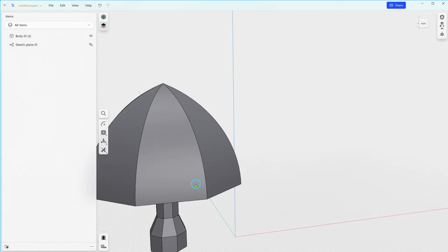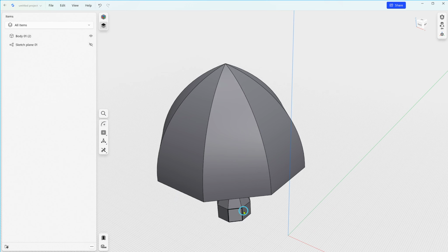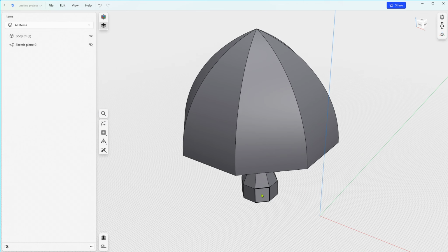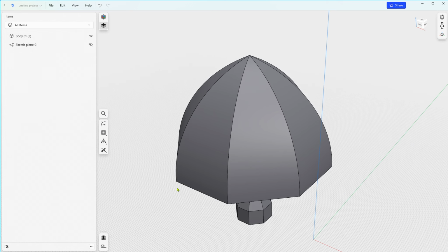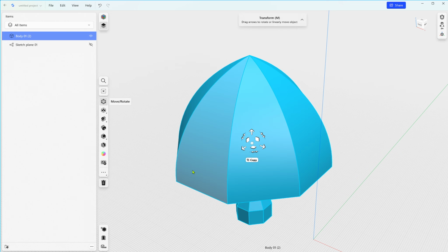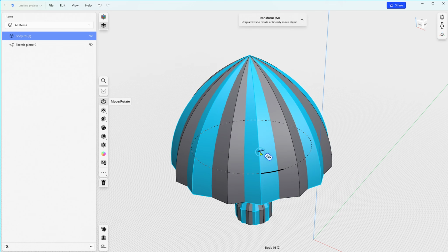There you go. Now you've got 8 sides on here. Now if you say, 8 sides for suckers, I need 16 sides, Stephen, give me 16 sides, do the exact same thing again. First time we did 90 degrees. The second time we did 45 degrees. So if we need 16 sides, what's half of 45? 22.5. So again, double click on it to select the full body, copy, rotate.